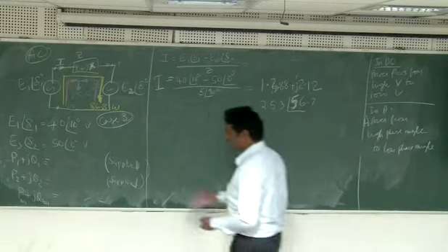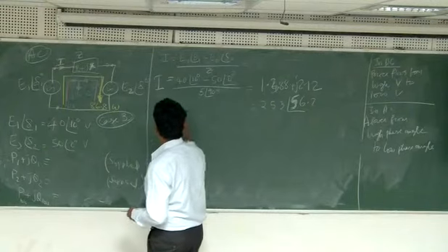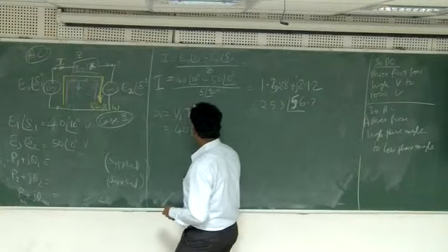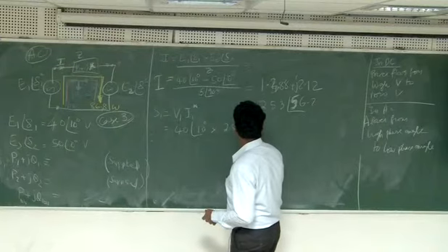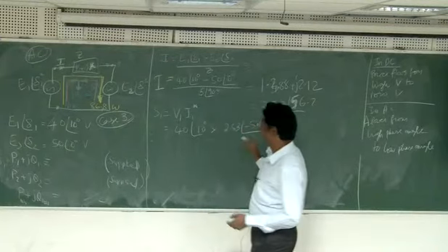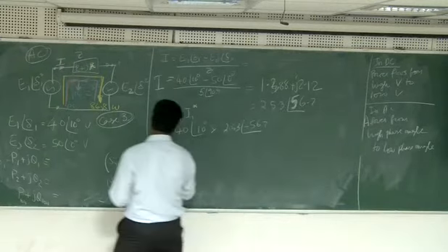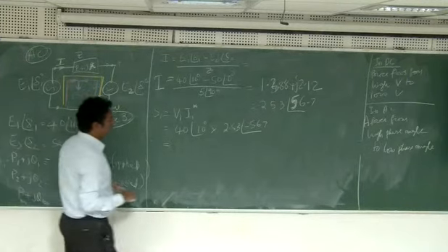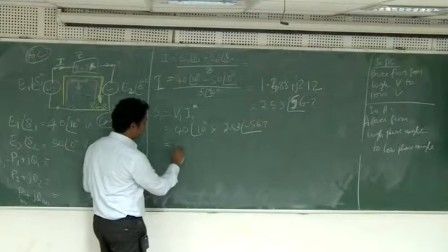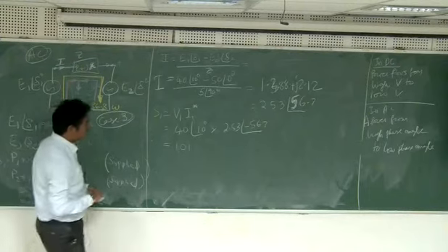Okay. So let's move forward and find out these two. So what is S1? V1 into I1 conjugate. Okay. That is 40 angle 10 into 2.53 angle minus 56.7. I have just changed the sign. Okay. How much is this? 101.6.